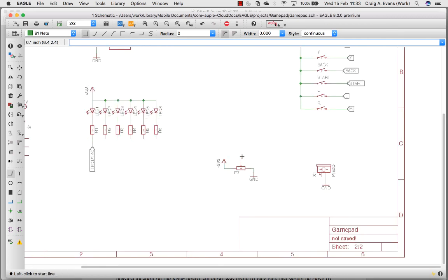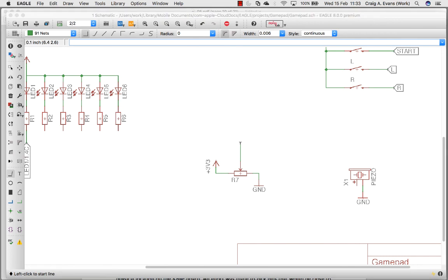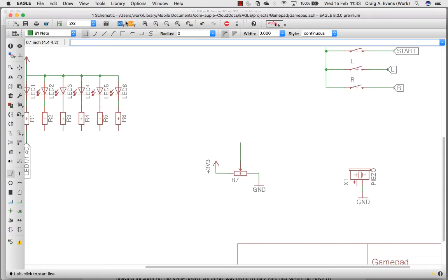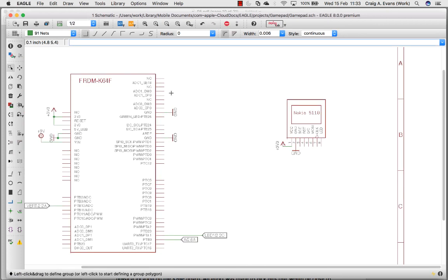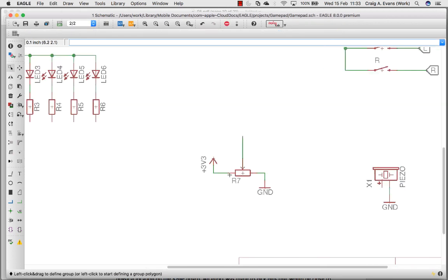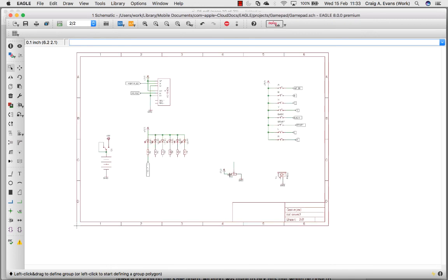And we can just do the same again, so add a net here, give it a label, and connect it to PTB2. So by using these labels, it's much easier, rather than having to draw loads of wires going everywhere. Makes your schematic much neater. So you should be able to fill in the rest of those tracks now to get your completed schematic.